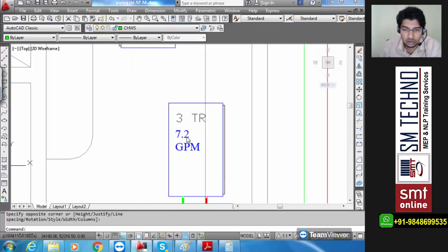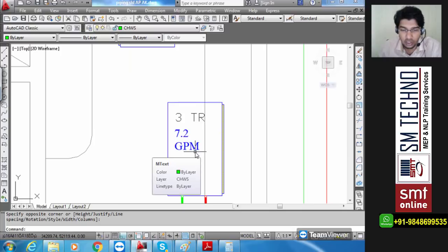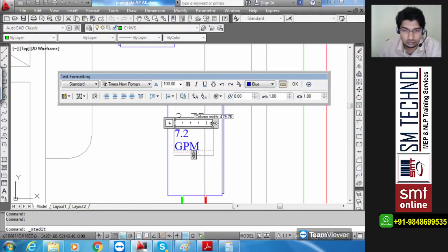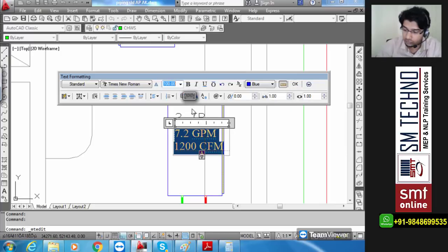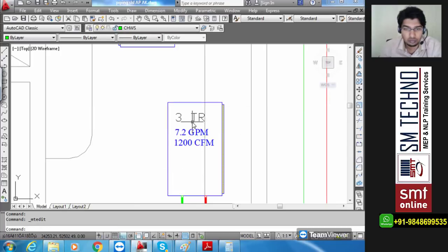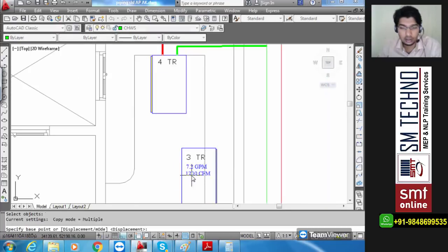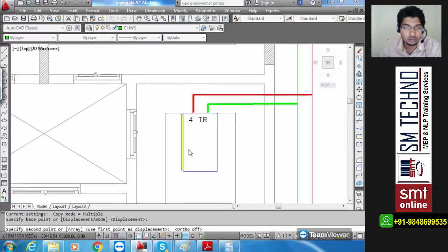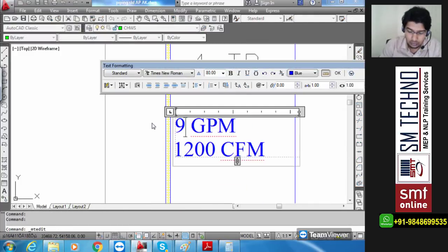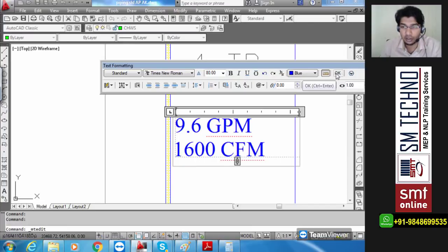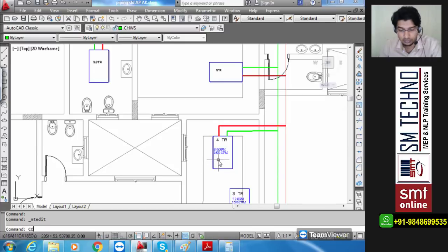I actually also need to mention the CFM. So tell me how much is the CFM for 3 TR? 1200 CFM. Confirmed? All right. Copy that. Next is 4 TR. 9.6 GPM, right? 9.6. Mary, are you following? 1600 CFM. Save. Next.